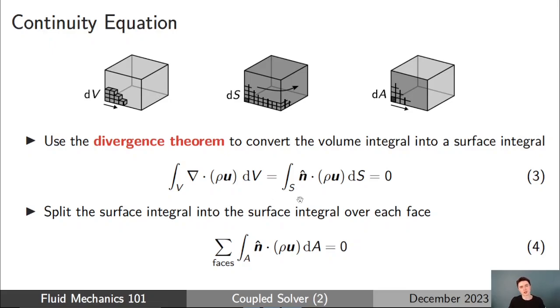And the next thing that we do in the derivation and the simplification is to note that the cells in our mesh are, of course, physical cells with flat sides. We don't have a smooth, continuous surface. The divergence theorem will apply to any enclosed surface. We have a cell that has a finite number of flat faces.